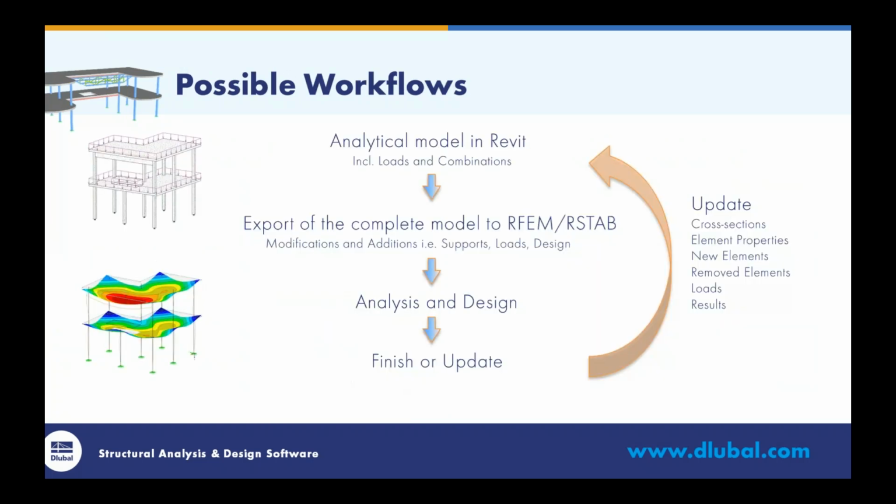The first workflow is maybe the most common one. You would start in Revit. So maybe the architect or the BIM manager created the model in Revit. And while he was defining the columns, the beams, the slabs, and so on, Revit allows you to automatically create the analytical model in the background. And this analytical model can be exported to RFEM, including loads in combination if you want.